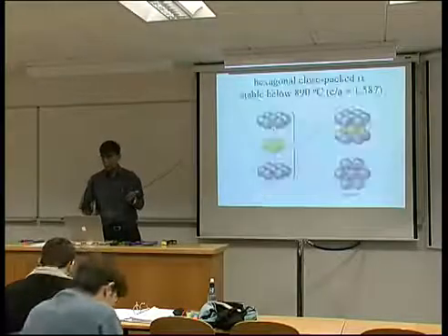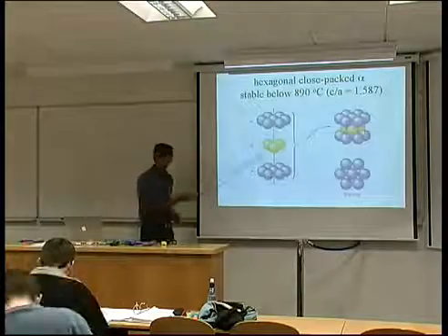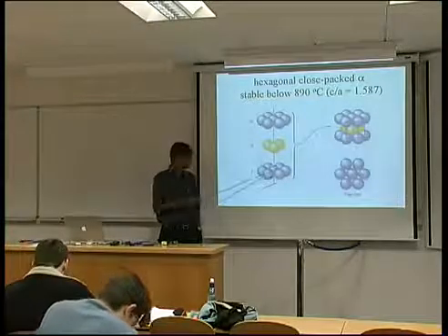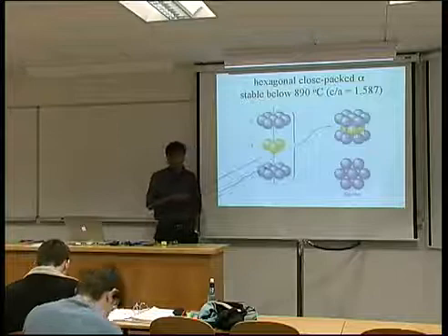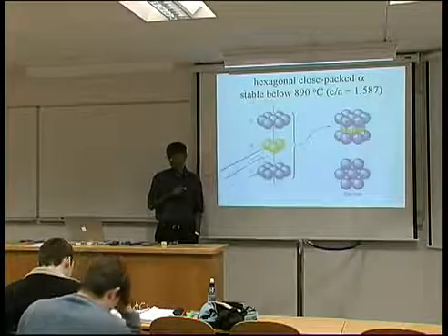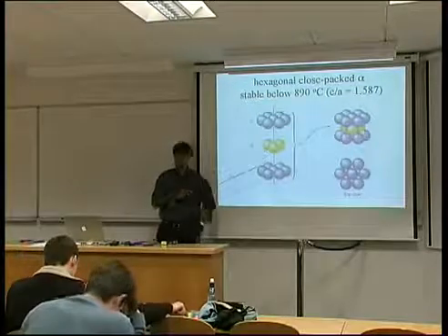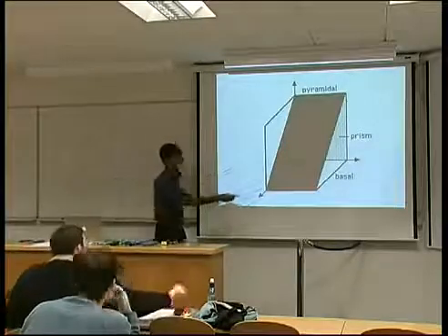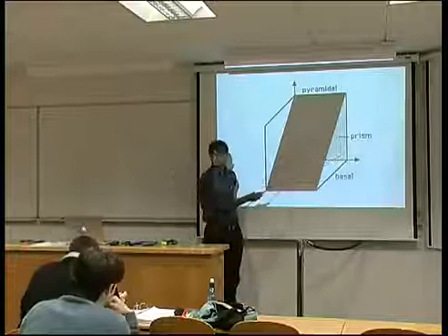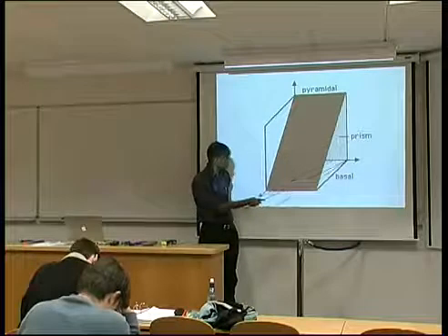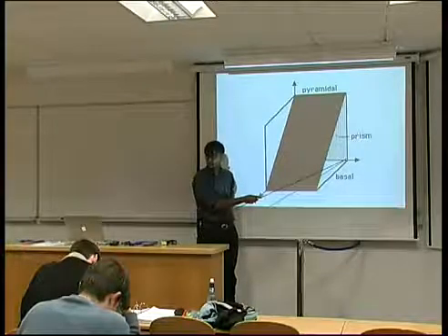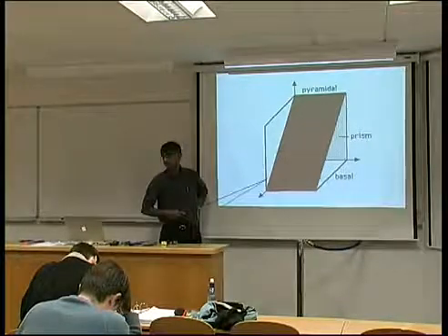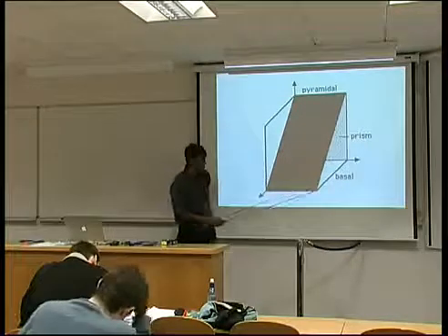And normally we say that, you know, there are only 3 slip systems. That means the slip plane is the basal plane, and slip directions are within the 3 close-packed directions within the basal plane, right? But in fact, titanium can also slip on this prism plane here, okay, because that also contains this close-packed direction, which is the direction of slip, and on the pyramidal plane, which also contains the close-packed direction.